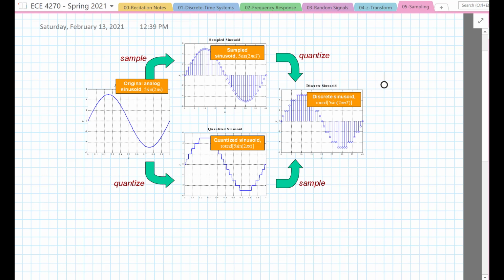We have an analog signal and we convert it to a digital signal essentially by quantizing the level, as shown in the lower path, and by quantizing the times at which we can view that signal, which we view in the upper path. Combining those two gives us a digital signal. In this section we're going to talk about both aspects of this, both quantizing the levels and sampling in time, but we'll start by looking at just the sampling process as shown up here.